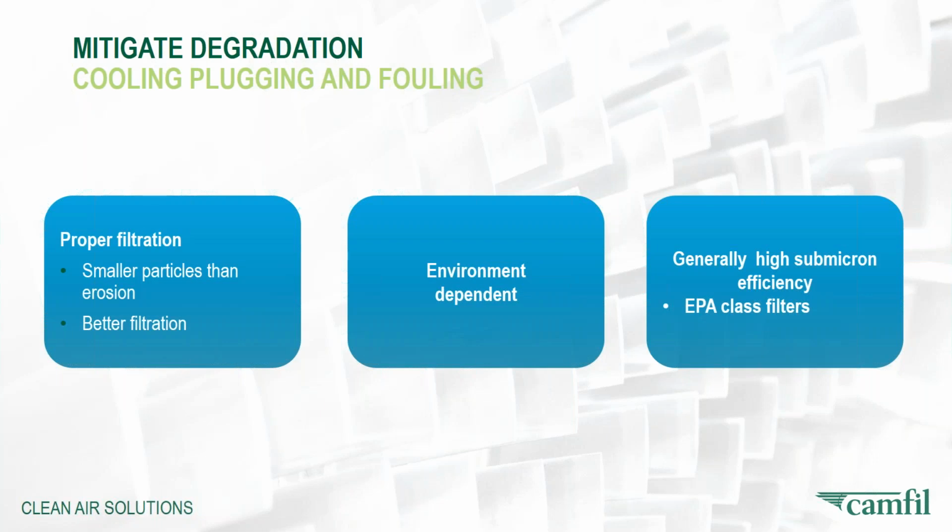Plugging of the cooling passages and fouling are mitigated in the same manner, because it's the same size of particles that we're dealing with. Smaller than the erosion side, 2 microns and smaller, and certainly many studies have been done, many papers have been written by ASME and others, that even submicron particles over time will adhere to the blades and degrade the performance. It's very much environment dependent.